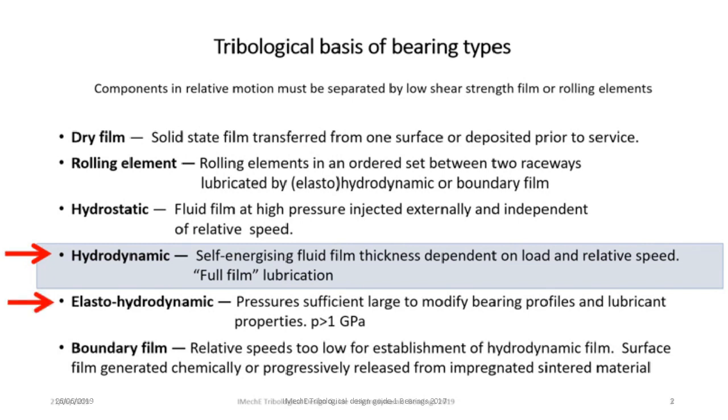Rolling element bearings and many other important tribological contacts, such as gear teeth, cams and followers, and other non-conformal contact geometries, rely on elastohydrodynamic lubrication. Under very high contact pressures, the viscosity of a hydrocarbon or oil-based lubricant can be very greatly enhanced, and in addition there will be local flattening of the metal surfaces. Elastohydrodynamic analyses can predict bearing behavior taking account of both of these factors.